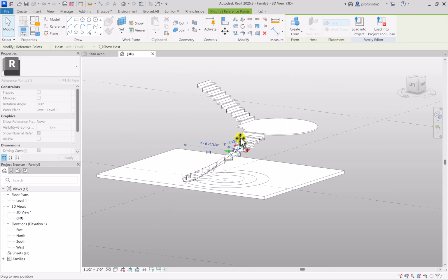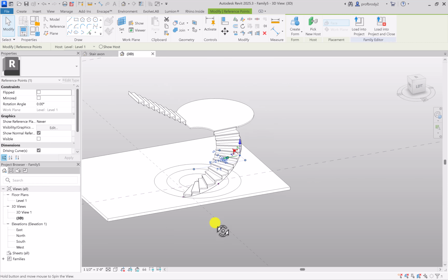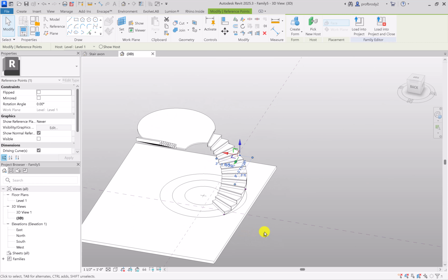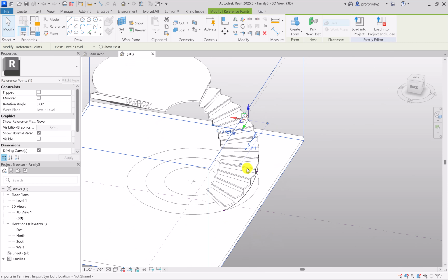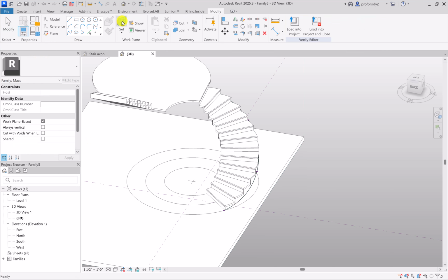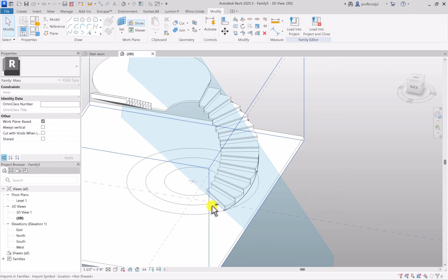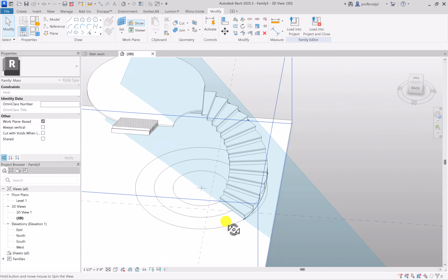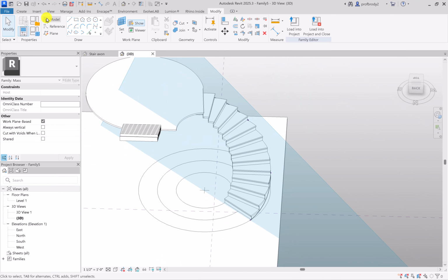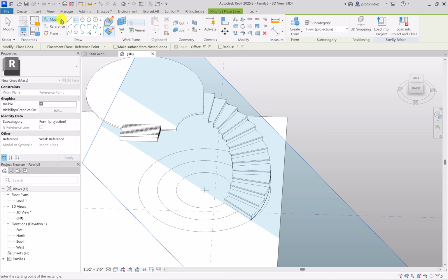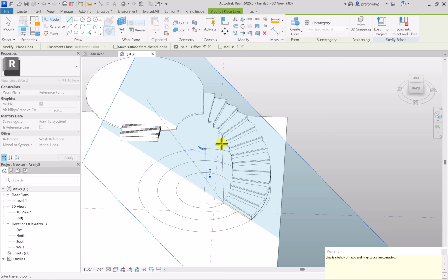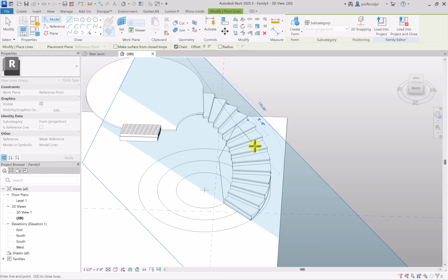So what happens is that you can actually attach a profile to this spline. You can draw in any of those points. They are now reference planes. So let's say I set my reference plane, and I could choose the show button. I'll click on this reference plane. I'm now automatically drawing in this reference plane. And let's say I just want a simple rectangle shape here. And here, let's make it a funhouse shape just because we have the option.